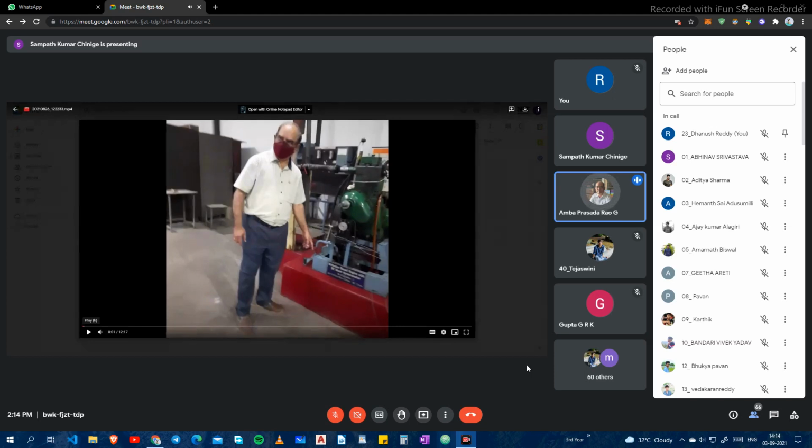Rated power and rated speed are the specifications given as per the make of the engine. As the name suggests, we are conducting the experiment on a Kirloskar engine. The nameplate details indicate that it is a 5 HP engine. 5 HP is equivalent to 3.68 kilowatts when it is running at 1500 RPM. With this background, we'll move ahead, and at any particular point you can stop and ask for any clarification.